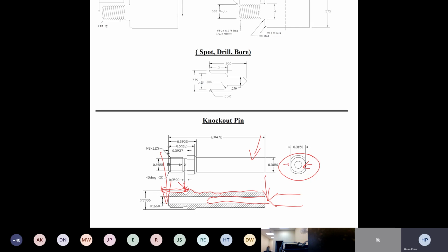So this is the side of the OD right here, and this is the side you want to order the collets for, the ones you're gonna put in the sub spindle in order to pick up the part. Excuse me. Okay, in case you're gonna order the guide bushing and you don't know the number, the collet is gonna be TD25.